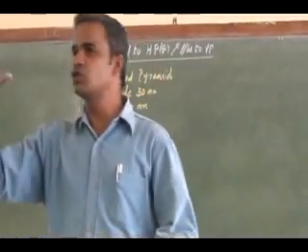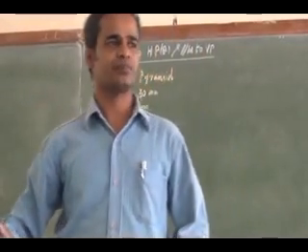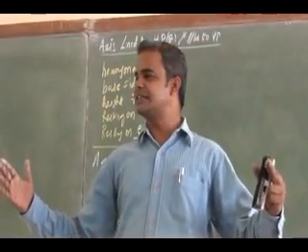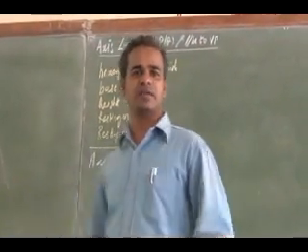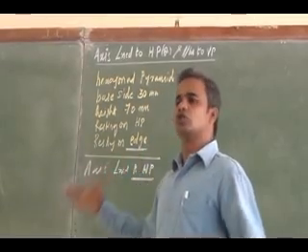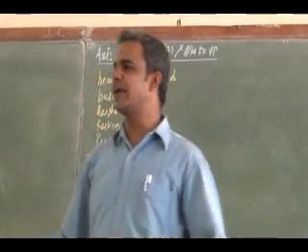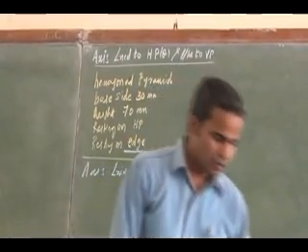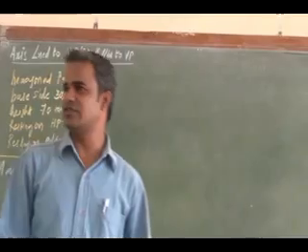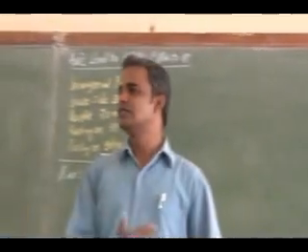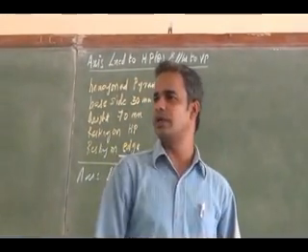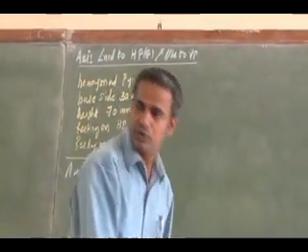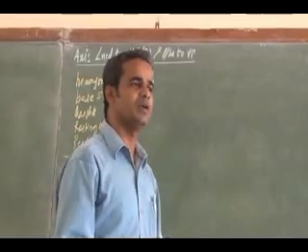As far as the hexagon is concerned, you have two orientations: keeping the edges at the extreme, or keeping the corners at the extreme. Since here it is resting with an edge, I have to draw the hexagon such that the edges are at the extreme. As a first step, since it is an axis inclined problem, I can assume the axis is perpendicular to HP, such that I can see the true shape of the base on HP.